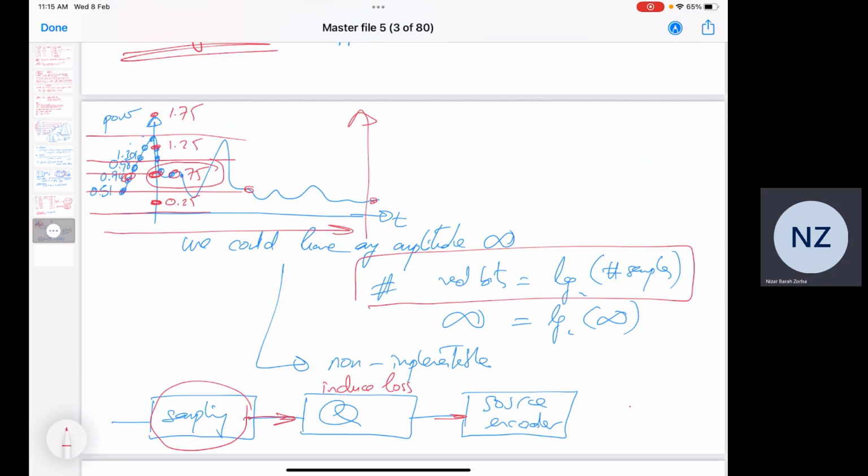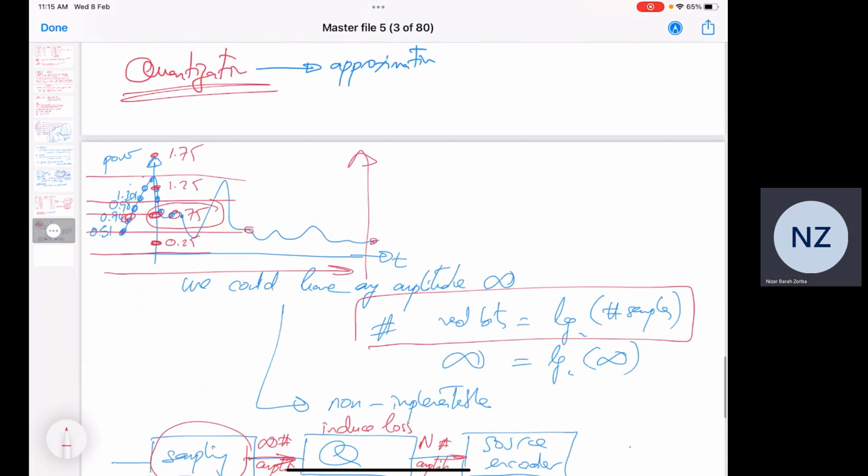So this is the same idea. I'm giving here 8 possible options. So here, of all the amplitudes, we only have 4 different amplitudes. This is what we call quantization. So the quantizer has an infinite number of amplitudes as an input, and it will give us a restricted number, n, of amplitudes. This n could be 100, but it's fine, I will work with it. It could be 1,000, it's fine, I will work with it. But it has to be specified, not infinity. Clear the motivation? Good.